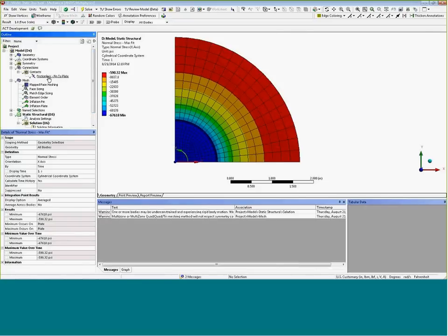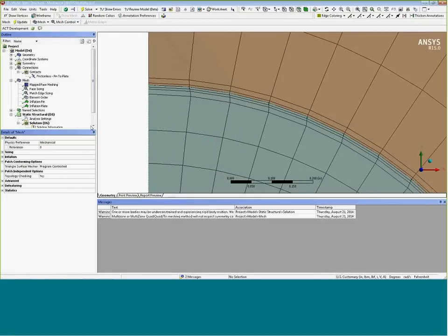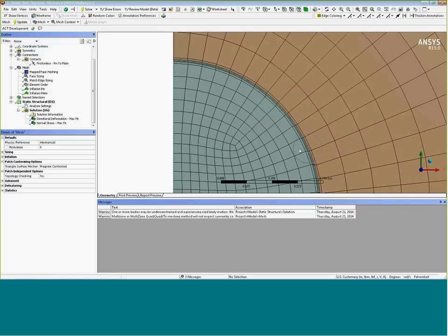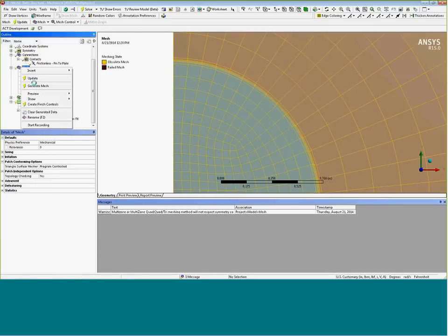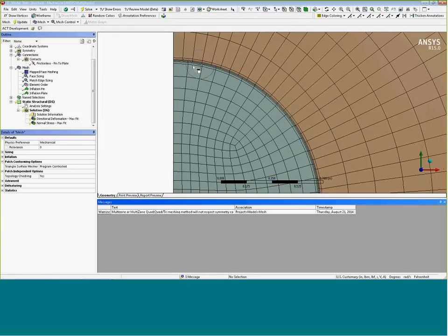So now these results look very nice around the circumference, but if we take a look at this mesh for a second, since we are interested in stress and accuracy of the solution we're getting, we see that this mesh is lined up node to node, or the elements are lined up, same number of divisions around the circumference. Very easy to do in 2D, but if this was a 3D problem, that's generally a little bit more difficult to have happen. So I'm just going to change this mesh so that way they don't line up anymore. Right, see, now we get different divisions all the way through here on each side.